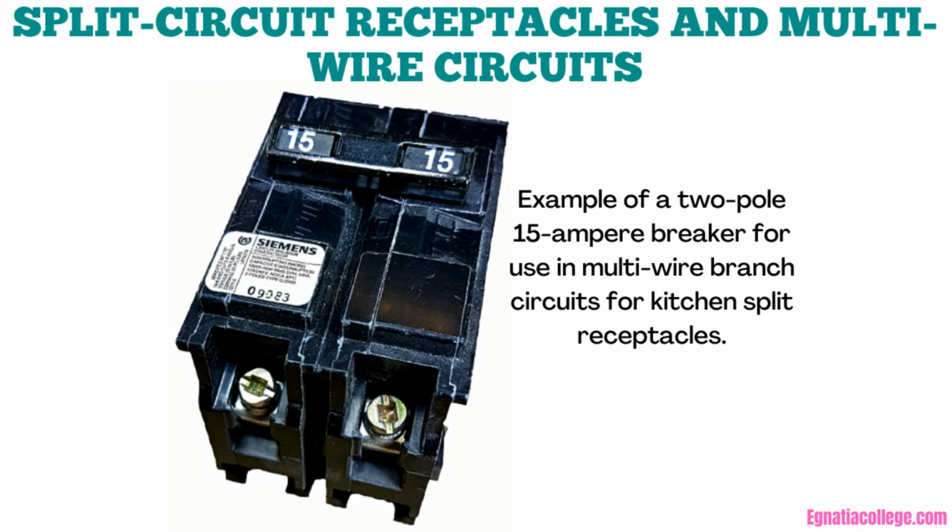When a multi-wire branch circuit is used to supply fixed lighting loads and non-split duplex receptacles, the continuity of the identified neutral conductor must be independent of the device connections. Instead of making connections of the neutral at the terminals of the receptacle, the neutral is tailed in the junction box and the tail is brought out to the receptacle. Rule 14-010b requires all of the ungrounded conductors of a multi-wire branch circuit, except for those supplying light fixtures or non-split receptacles, which are connected to the neutral and one ungrounded conductor, to be disconnected simultaneously.